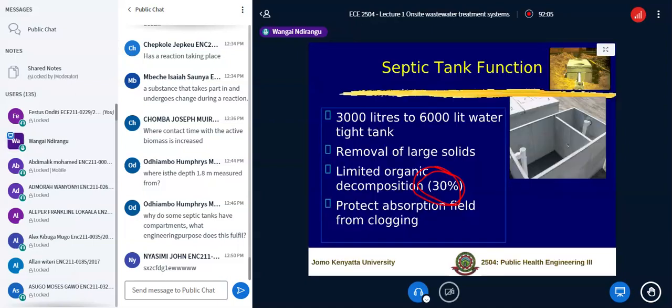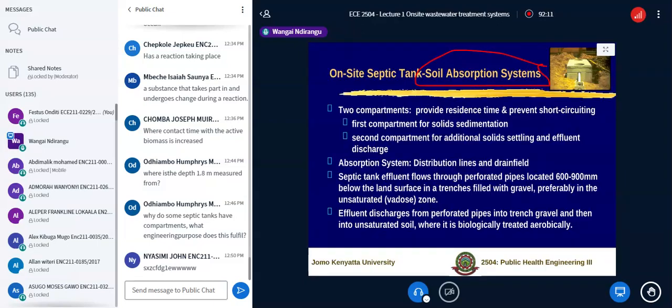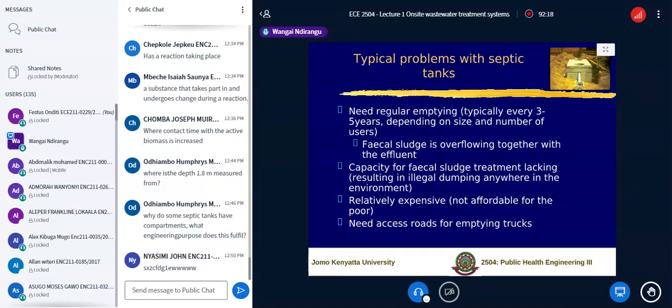Now, I did mention already that BOD is removed at that level. And we were talking about the soil as being both the treatment and also the dispersal media. And we'll come to that, but we see that the septic tank, again, very important, remember, is not a maintenance-free facility. It needs to be dislodged; between 2 and 5 years is really extreme. In fact, for me, I say every 2 to 3 years, it needs to be dislodged.